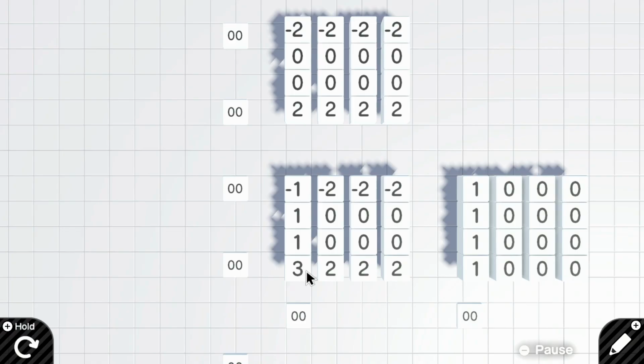Since the lone number is 3, instead of sending 0.00006, I'm sending 0.00004 instead, so that when 2 of them are added together, it'll be 0.00008, so it's still not enough to break the threshold, and only when there's 3 signals together will the logical input be able to activate, since it becomes 0.00012.